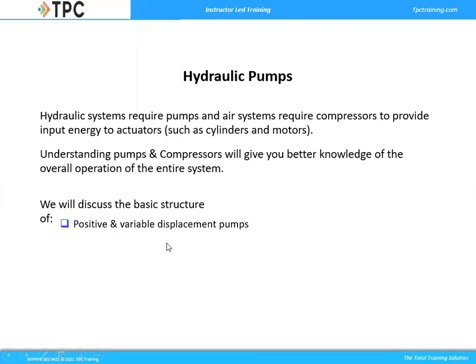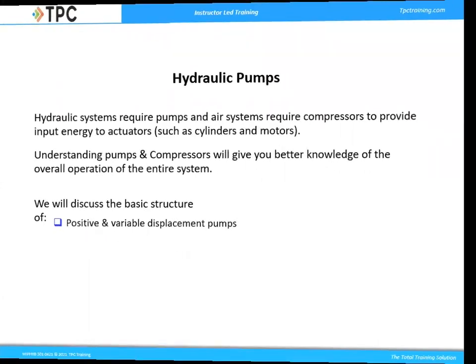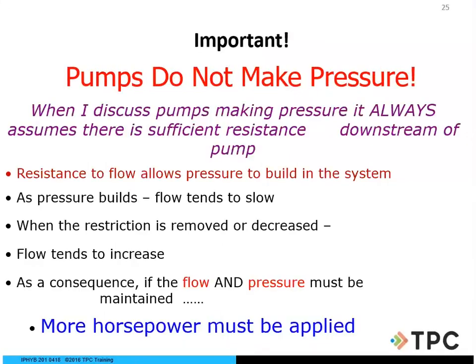There are positive and variable displacement type pumps. What pumps are there to choose from? A lot. Just remember, our pumps do not make pressure. They create or establish that flow. We need flow. Whatever our piping system is, our hose, or let's just say, for example, black iron pipe and so forth, going out to the discharge, that is what really creates our pressure there.